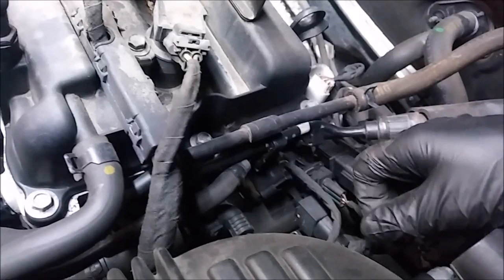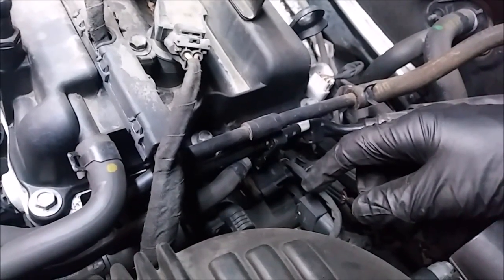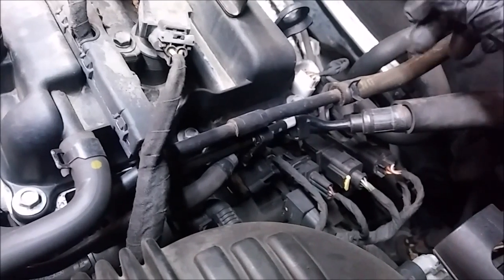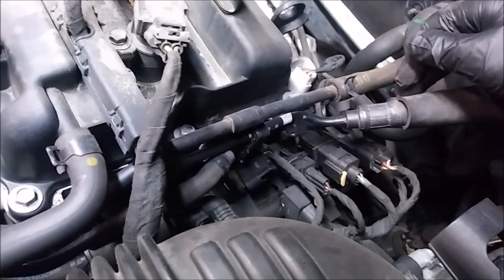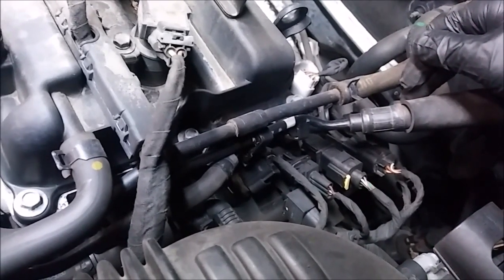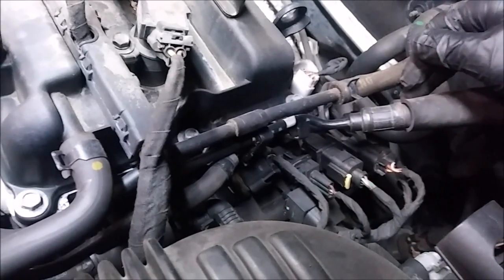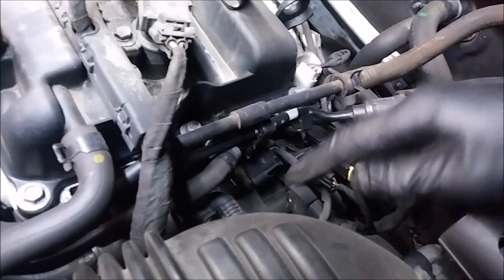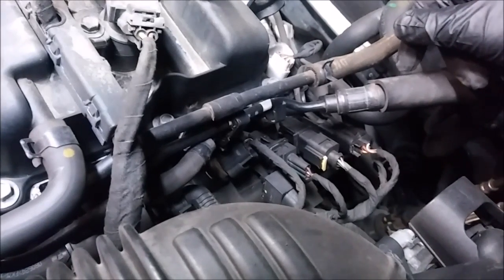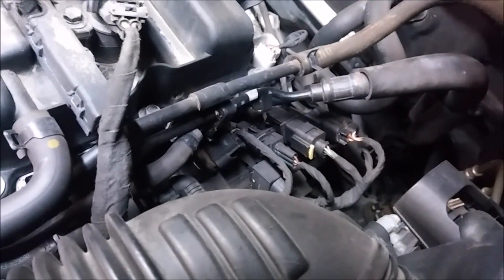So that's a really quick, easy check to identify a leaking purge solenoid. It's something we're going to have to do anyways to smoke test the system, because I'm going to use this hose to plug the smoke machine into. So we're kind of getting two tests in one by disconnecting this hose and this connector. So I'm going to get all that disconnected, and then we're going to check for vacuum out of this purge solenoid in its de-energized state.